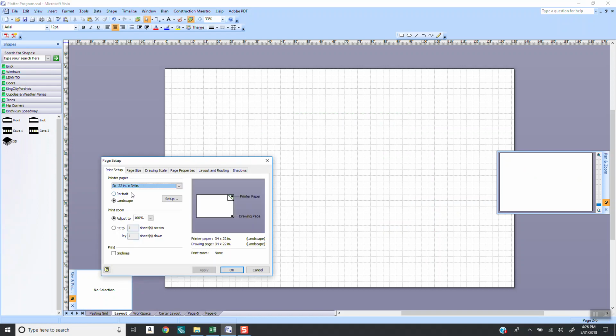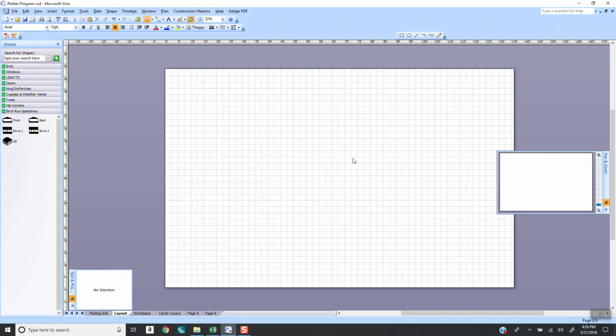Yes, there we are, D size paper, so 22 by 34. I have a 24-inch roll plotter, so I set it to D, or architectural D will come out at 24 by 36. This is just a little undersized. But by doing this, setting your paper size and then calibrating it, you shouldn't have to touch it again after that. Okay. So I hope this video was useful to you.